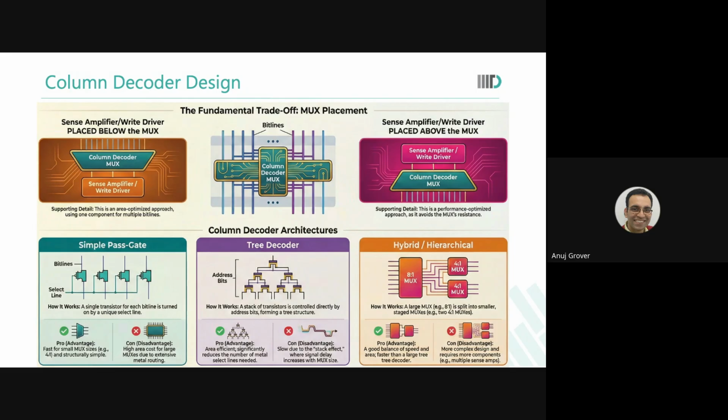See, in SRAMs, what could happen is that if one particular bit line has a lot of zeros or ones written on it, then the other side can discharge very significantly if there is no constant charging mechanism. What that can lead to is that the one that you had stored inside the memory cell can start to leak from the pass gate, which is off. That is why I'm using the term leak. And that can result in degradation of retention voltage.